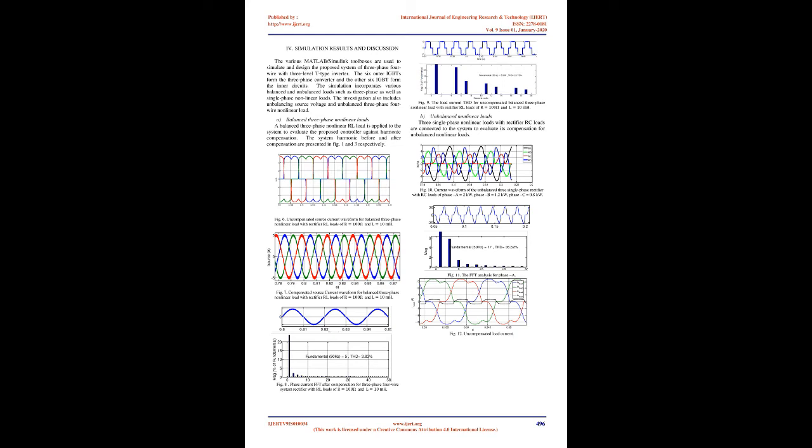The asymmetrical linear and/or nonlinear harmonic in symmetrical nonlinear load causes the imbalance phase current. The imbalance phase current in any phase causes the neutral point current and further aggravates the neutral point imbalance. The system reference and disturbance signals are usually an odd harmonic frequency of the power system. Therefore, the repetitive control is the best choice to introduce an infinite gain at a submultiple of these harmonics below half of the sampling frequency, i.e.